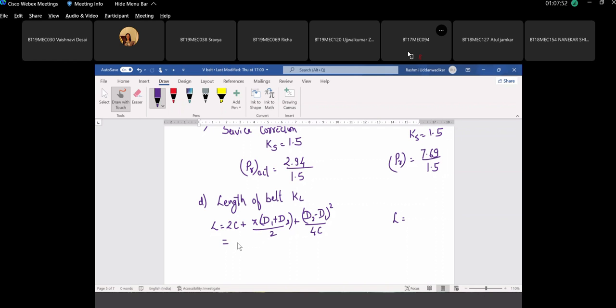Saurabh, what is the length for C? 2351 for B. And in the design data book, for the cross section B and for this nominal pitch length, what are the standard values close to this? Check the nominal pitch length for cross section B. 2351 is your answer. The adjacent values given here are 2329 and 2507 for B.